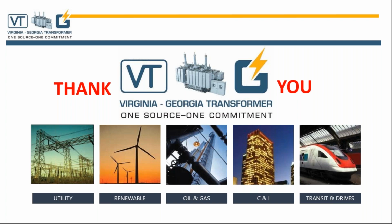It allows the path to flow, but the voltage increase at its terminal will really change your V by T of the design, the volts per turn. So that is not solved. The delta connected tertiary winding will act as a stabilizing winding, providing a path for the third harmonic, which is a zero sequence. So it may reduce the effect, which I don't know fully now, but it will not fully solve your overall voltage problem.